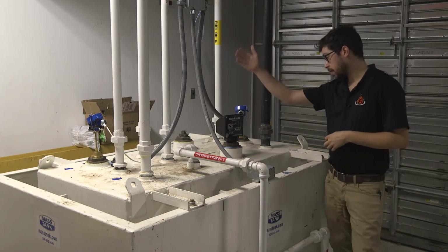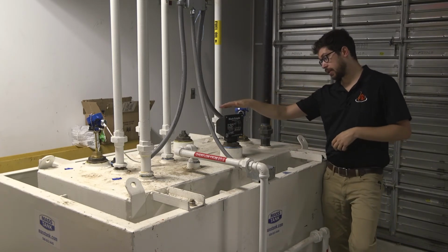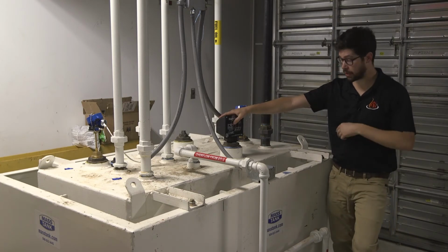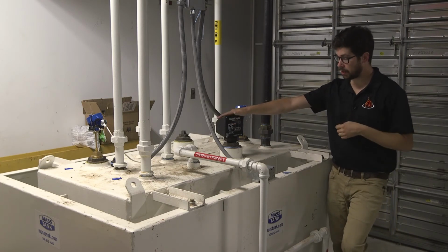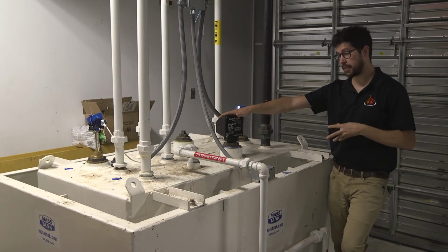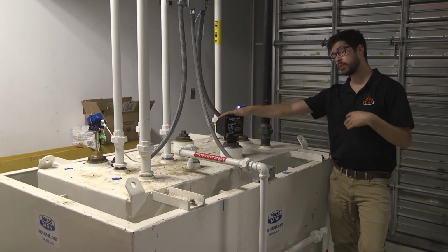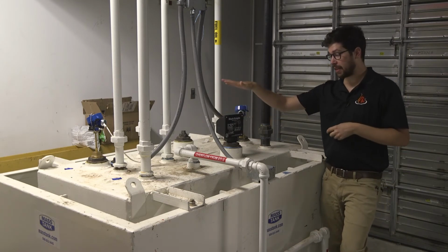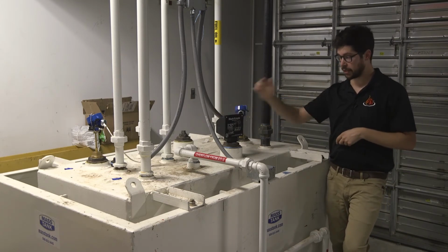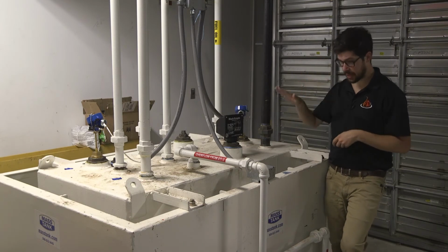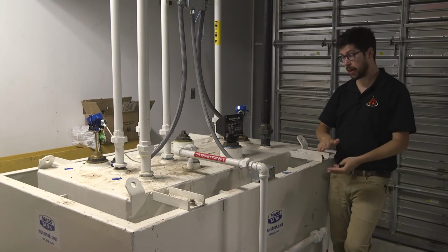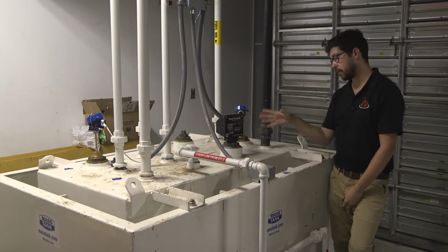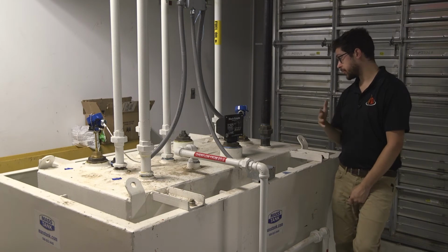We have a physical level indicator, which is slightly different than the other one. The other one is just empty to full, where this one is inches to empty. Weird way to say it, but the thought makes sense, the level is 27 inches. So inches to empty meaning inches to nothing, but that's also just 27 inches off the bottom of the tank. And that was all just set up during commissioning.